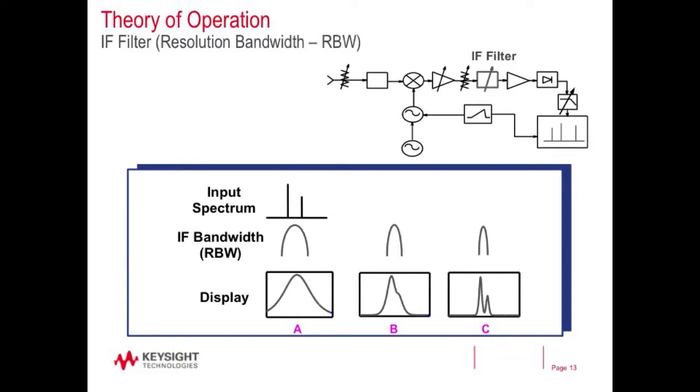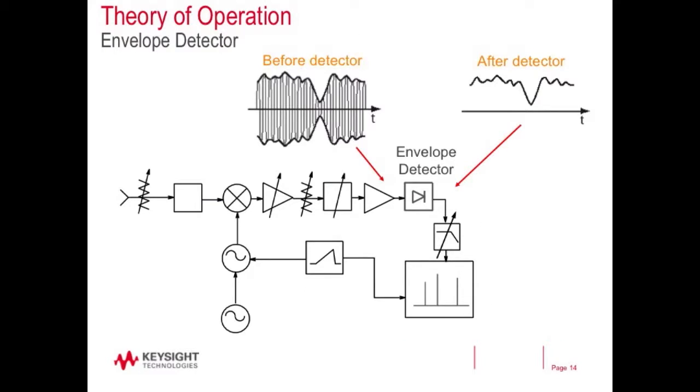After the filter, what's often called the resolution bandwidth, there's what we call the envelope detector. This might be the signal going into the envelope detector, and we depict it as a diode here. This is what it looks like afterwards, and you can see it strips off the envelope of this modulated carrier. We strip that off for further processing.